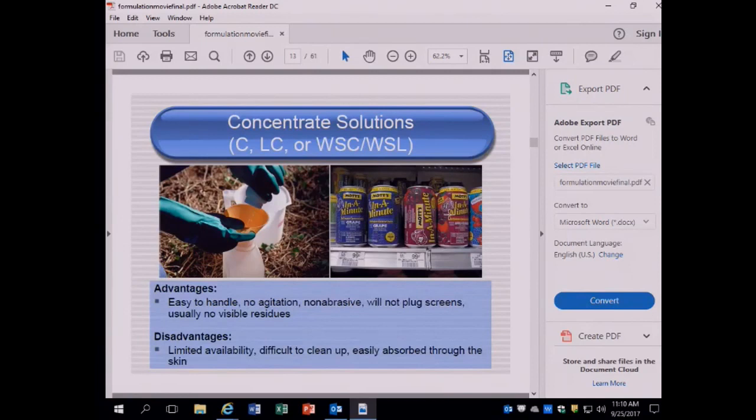Some of the spray machines will have a bypass system on it. When the pump is on, it will provide pressure to the boom or the nozzle, whatever you're using to apply the material, but it'll usually have a valve in it that will reduce the pressure and throw the bypass into the bottom of the tank, which will create an active agitation through the additional circulation there.